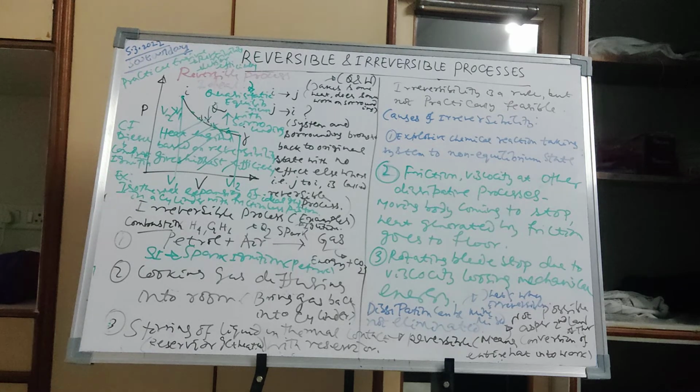in a diesel engine you don't have a spark plug. The combustion gets initiated by compression. The compression ratio of a CI or diesel engine is very high. So you compress the air to such an extent that the pressure rises, and when pressure rises, temperature also rises. So when you inject the atomized fuel from the nozzle spray, the ignition automatically starts. So the ignition starts by compression itself. That's why it is compression ignition. Whereas in an SI or petrol engine, you have to have a spark to initiate the ignition. So the compression ratio is less in the case of